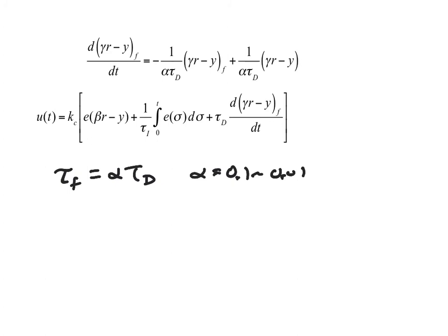You'll also note that we have now a set point weighting factor beta, and then we also have a gamma term shown here. So you'll see this as part of the two degree of freedom expression when you use that function in Simulink.